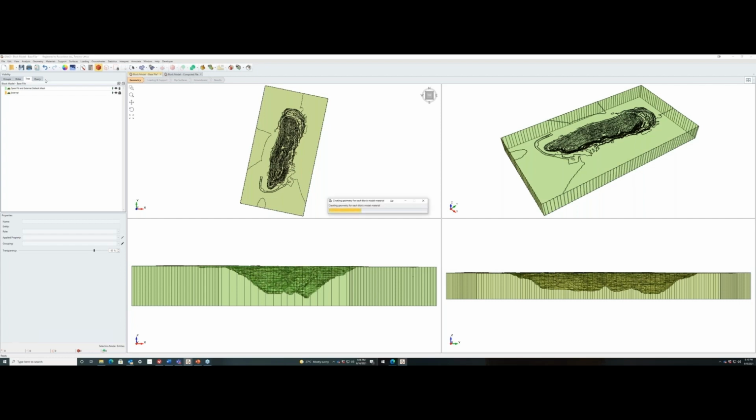So it's doing that still, but you can see already this is now jagged because it's bringing in blocks. So the block model has been brought in. As you can see, you can now see the different material zones, the yellow, the sort of purplish, which is the phyllite, the yellow is, I believe, the mafic intrusion, and that's the surrounding sandstone host rock. So it has created this geometry out of the block model.